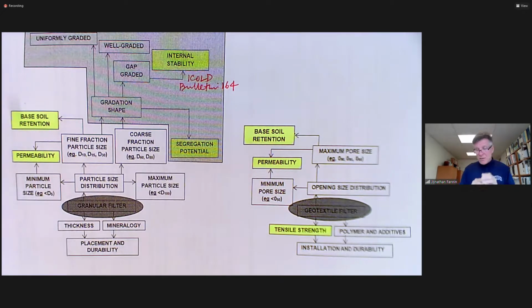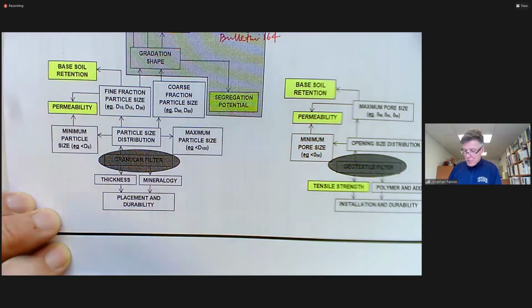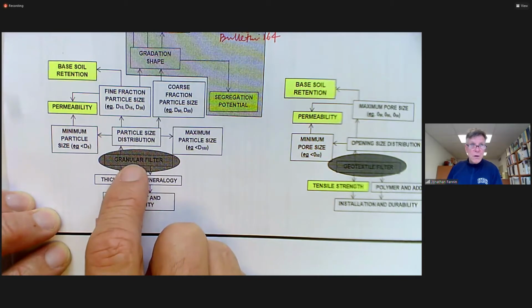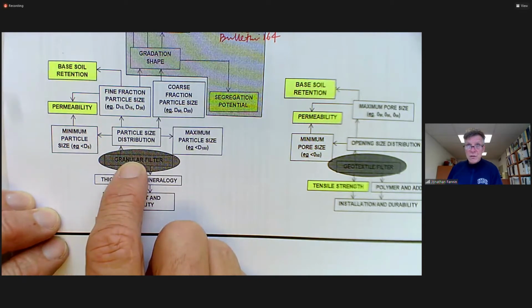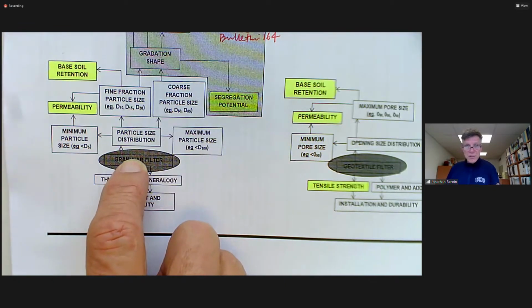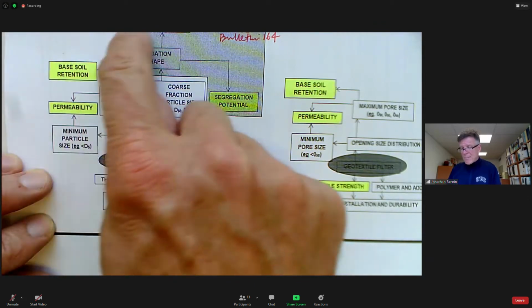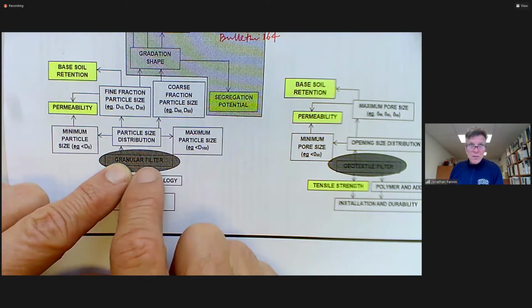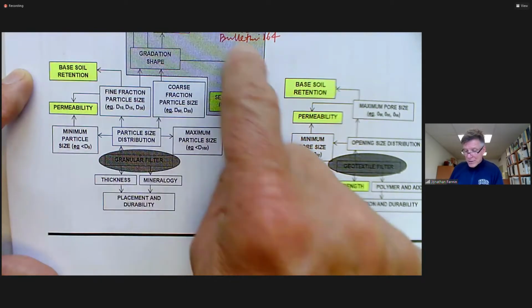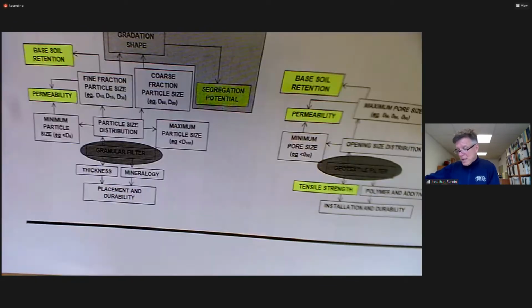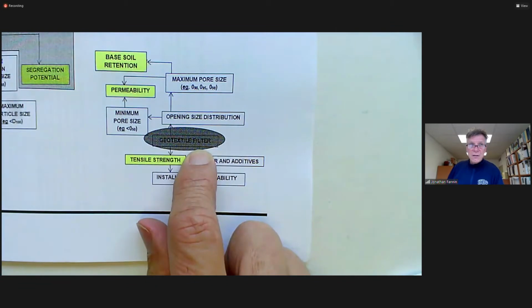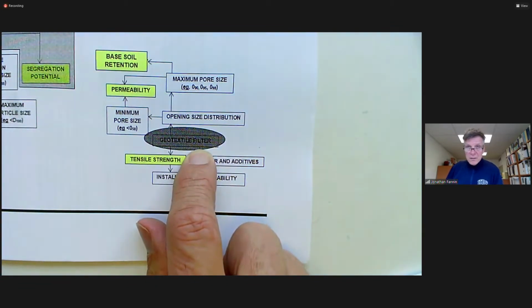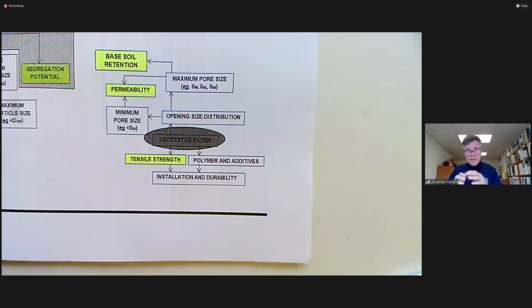In fact, here's another perhaps interesting take. By and large, you're going to try and source your parent material for the filter as close to your project as possible. And then you fabricate your filter on site, arguably. I'm thinking of dams, for example. So in contrast to sourcing the material as close to the dam site and fabricating the filter on site, with a geotextile, you source and fabricate the geotextile off-site and then deliver it. In fact, you fabricate it under, one would expect, very well controlled conditions.